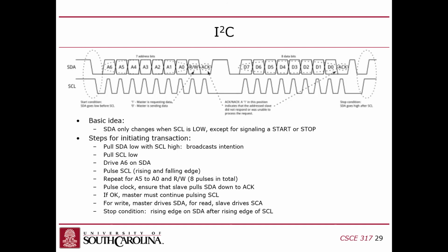You should never do that if you're sending data, because that is how you signal a start and a stop signal. Make sense? So when clock is high, if you drop the data, that's a start or a stop. It's a stop if you've already started. You guys with me?